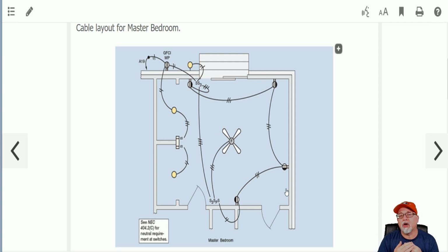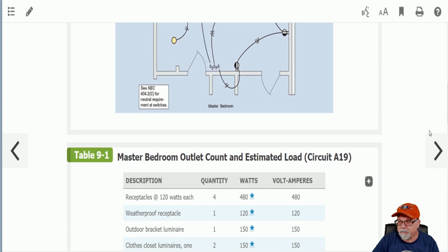To be honest with you, I'm going to go out to what the code allows me, the maximum. I'm going to go out 6 feet, unless it kind of screws with my layout. And then I've got to look at the layout of the wall. I'm never afraid to add additional receptacles. They add very little cost to the job, but it might be a convenience thing, and it might separate you from the low-end electrical contractor versus the high-end, which doesn't nickel and dime your customer. But again, that's your decision. I don't get into the cost aspect of that. It's just things to think about.